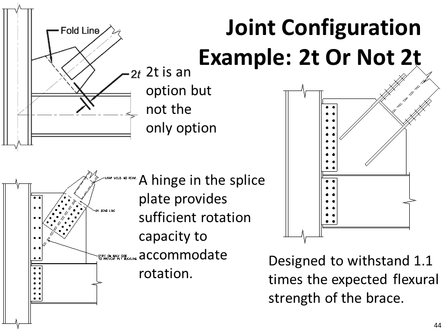And then there's also an option where, if the brace is going to buckle in plane of the bay, then there's a requirement to develop the expected flexural strength of that brace, accounting for strain hardening. So that's the 1.1 multiplier there. And any one of these connections that are shown could be used to satisfy the requirements of the seismic provisions.